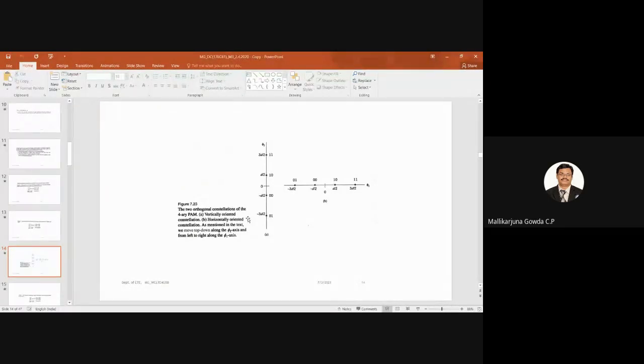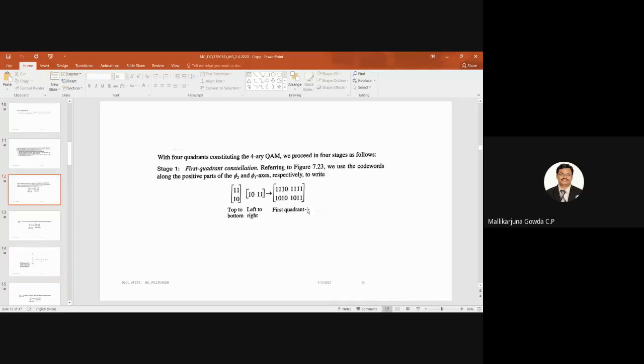So first you write the horizontal constellation diagram. Okay. Then for the vertical, if I make this vertical constellation diagram horizontal, just see how it will be. Same, no? It starts here, then next this one, 1, 0, then 0, 0, then 0, 1, right? So just the multiplication of these two yields the M-ary QAM signal constellation. Hope this is all very simple to understand. I hope you have understood how you can write that.